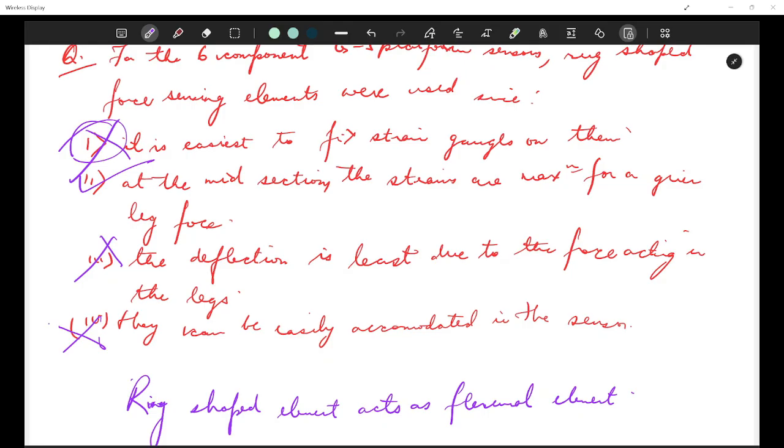What happens if friction exists? When external forces are applied, some force would be lost in joint friction and not fully transmitted to the sensing element. So the measured force won't be equal to the actual force. This causes inaccuracy and poor repeatability.